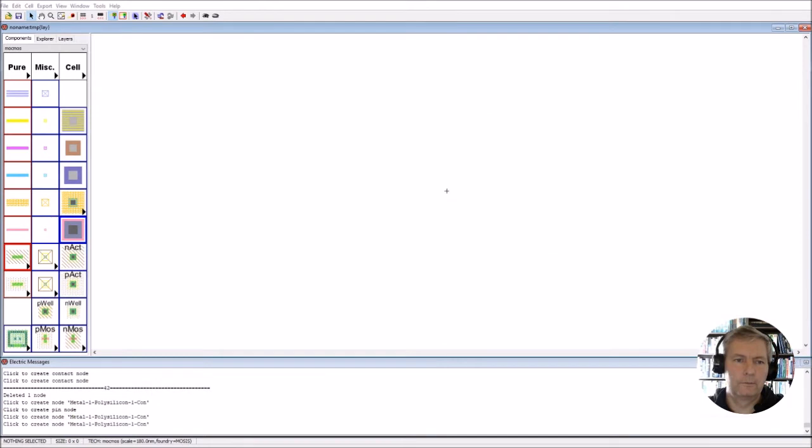So that's us talked about all of this lot here. Okay, so we've got the different layers that we can get access to, and we've got the contacts which allow us to draw those layers on the screen, and we've got the vias which allow us to contact between these different layers. We're going to cover this little section here now.